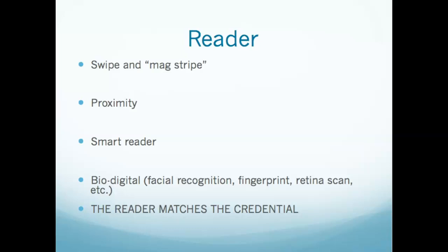You've all been issued one, I think. There are proximity badges, which are badges that have an antenna inside, and it can be active or passive. It can be battery powered or not. Usually it's not. You just hold it within a few inches of the reader, and it sends the signal to it. That's what I generally use if I'm using badges, is proximity.